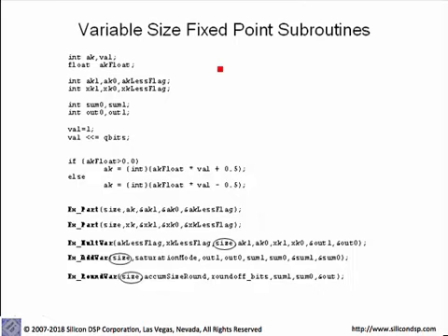In these cases, the particular architecture can be modeled using the fixed point routines shown over here, and you can use the existing source code for the, for example, Cascade form and direct form filters in order to model the architecture of your particular FIR or IIR filter that meets the requirements for your higher clock speeds.